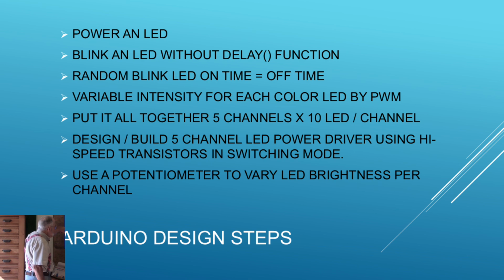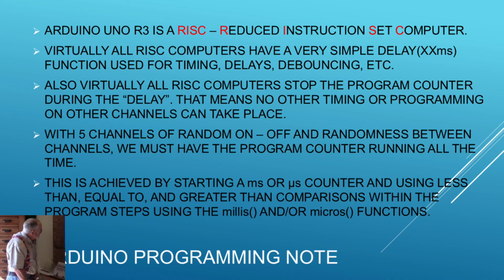All right. And we're going to use an LED to change the brightness per channel. Like I said, also because your eye can only resolve a tenth of a second. Yeah, that's true. So if you take an LED that's pulse width modulated, fix your eyes and you move your head across, you see a bunch of dots.